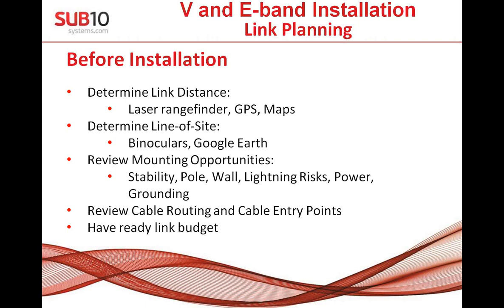The easiest for me every time: if the customer knows where the link will be installed, simply use Google Earth, because you are able to find the buildings or places where the mast will be located. With these two places, you can easily calculate all other data which are necessary for the calculation. You are able to see the link length on Google Earth, and you can also find the altitude, which is good to know also for the calculation.